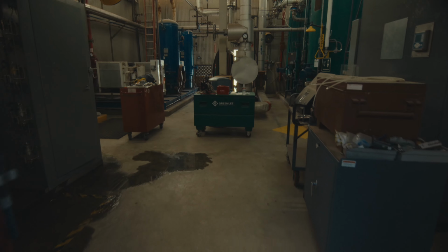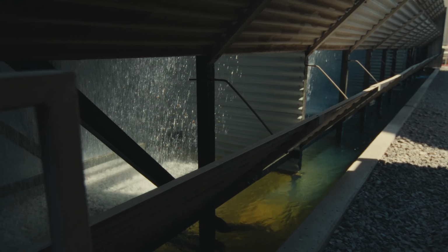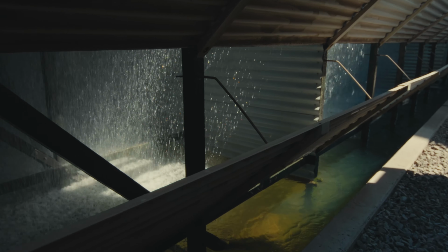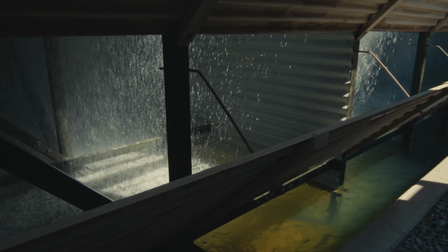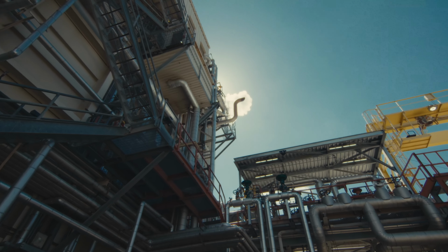So getting as many cycles of concentration as possible while still maintaining control and minimizing consumption of other items will ultimately help you achieve your water conservation goals. What's important to know is many cooling water treatment programs are generally limited on how many cycles they can operate at.